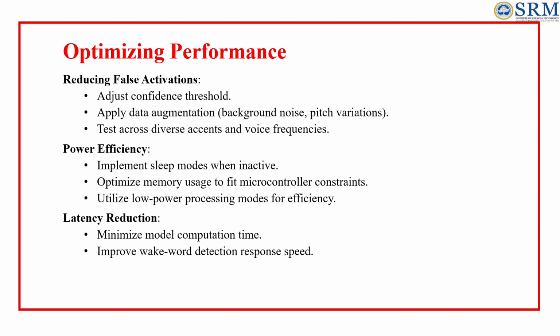Last one, latency reduction. Finally, we want the system to respond quickly when it hears the wake word. To reduce latency, first, minimize model computation time by using a lightweight neural network and a quantized model. Second, streamline inference so that classification runs in milliseconds. This ensures that when we say the wake word, the device responds instantly, creating a smoother user experience.